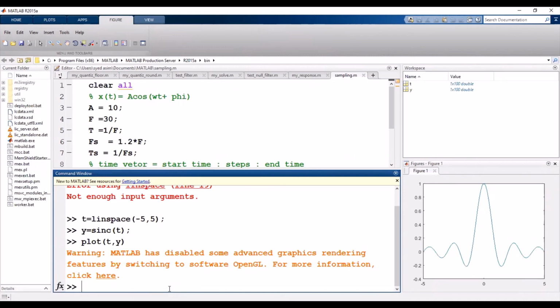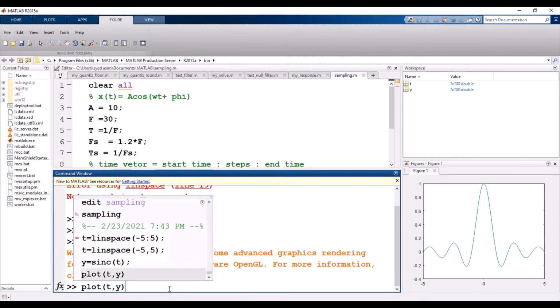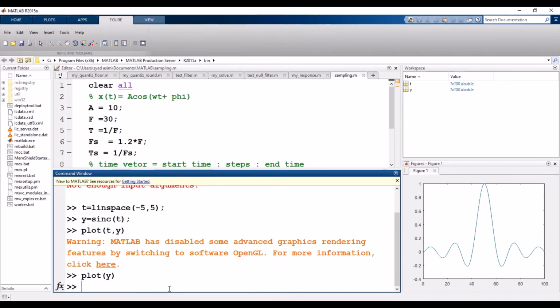Now these values are stored in the y variable, from 0 to 100, because in MATLAB we don't have any negative index. If we simply plot y, we can see this whole signal exists from 0 to 100, so we don't need to give any shift to move to positive time indexes. It is already stored in positive time indexes. So what we need to do is just calculate the impulse response.